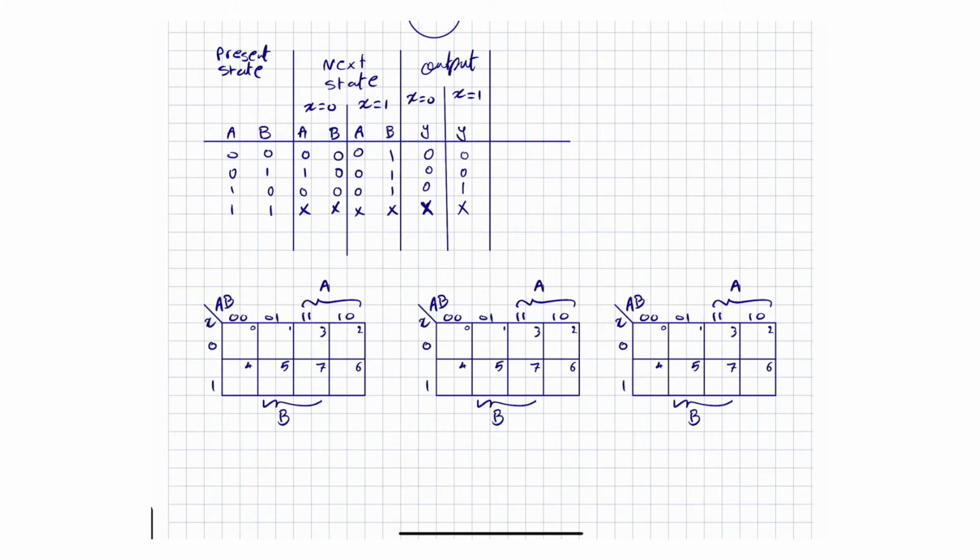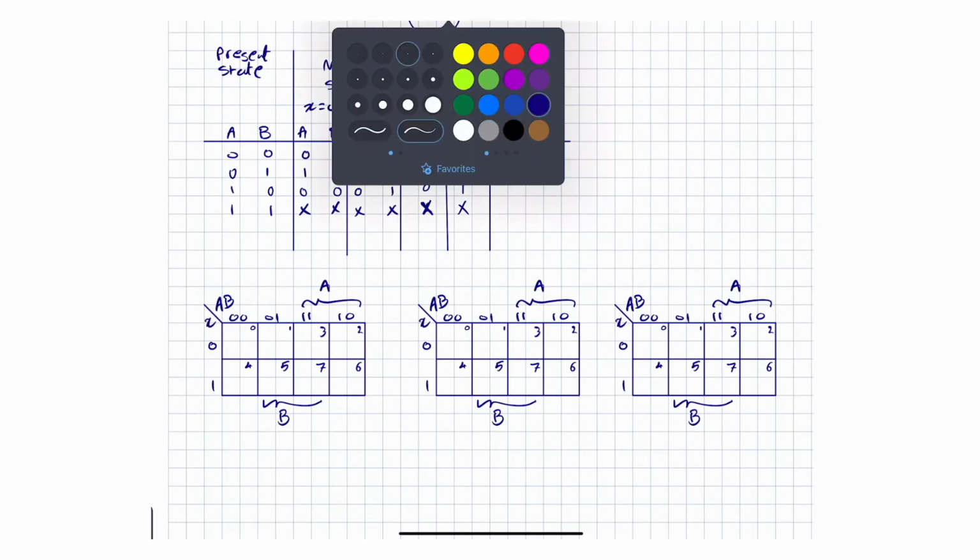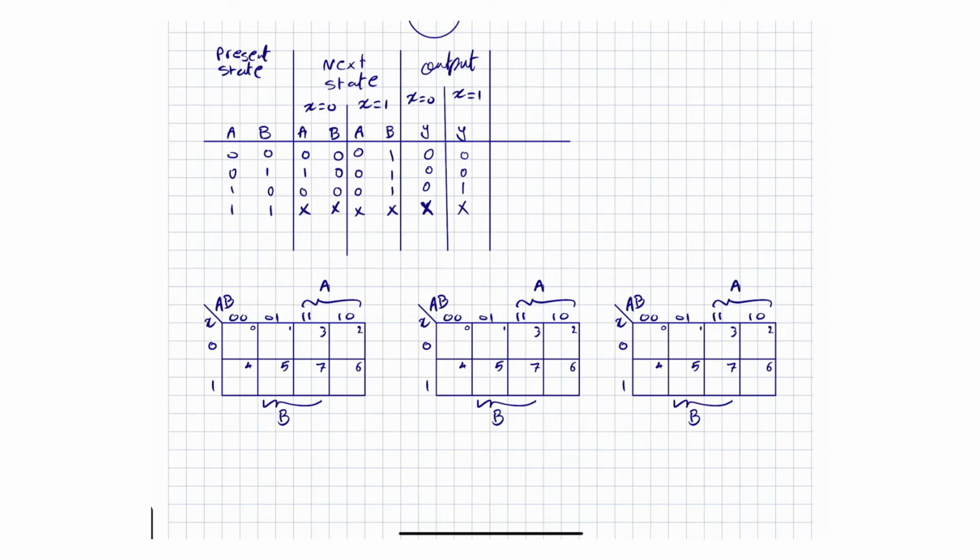So I've designed these 3-variable Kmaps and hopefully they're correct. But anyway, what we need to do is figure out something for the flip-flop. Let's say this is for flip-flop A. So I have to take a look at this state table and fill these Kmaps from the state table. For flip-flop A, if this is X, so these are X0, I'm looking at these particular 1s and 0s pattern. So what I really have is a 0, followed by a 1, followed by X, followed by a 0. And the pattern for X equals 1 is these ones in here: a 0, 0, X, 0. Okay, and then I can fill out the rest of them.